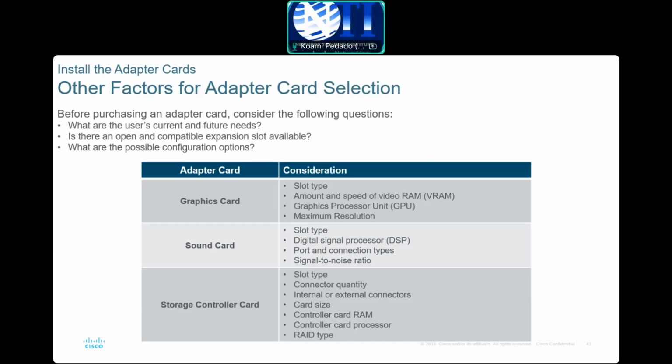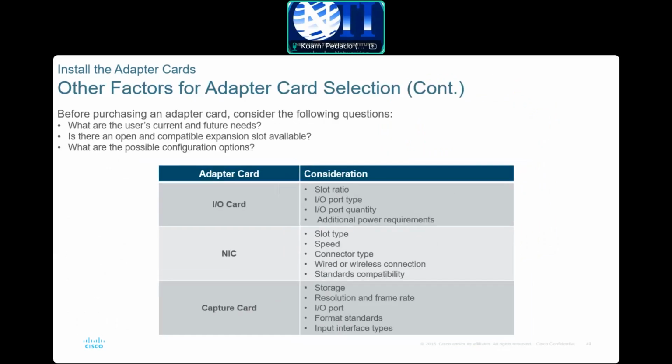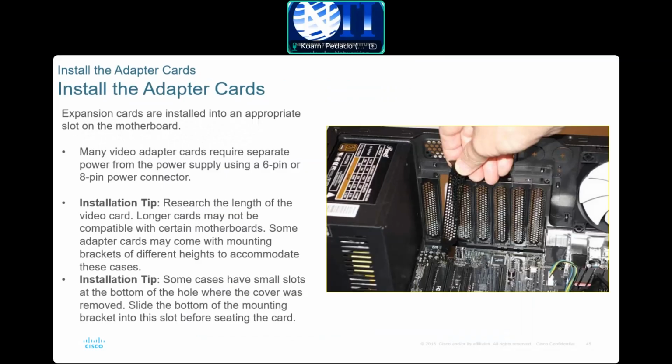And then the sound card. If you want to put a graphic card or any card in an expansion slot, you will see this bracket. Those are just brackets to protect it, so dust doesn't go inside. You remove this when you put the card in, so that, for example, the video card will reach out and you can plug in the cable. So you need to remove this bracket. It seems you can just pull it out.